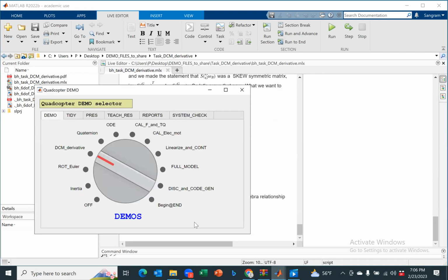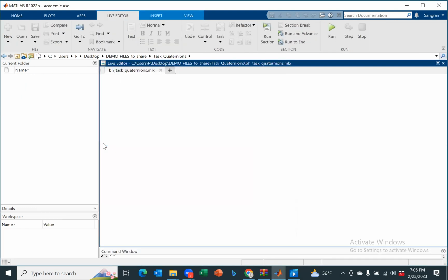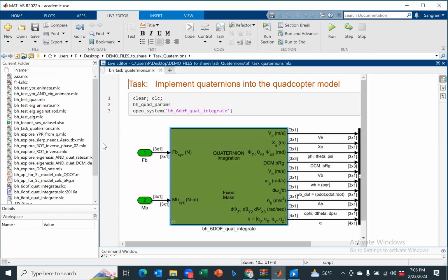The next part is if you want to implement a quadcopter. Again, it doesn't give you theory, but specifically it gives you the quadcopter block, wherein you can change the vehicle parameters and then just feed 3 forces and 3 moments, and now you have all the output that you can feed to your simulation. So I would encourage you to play with this.